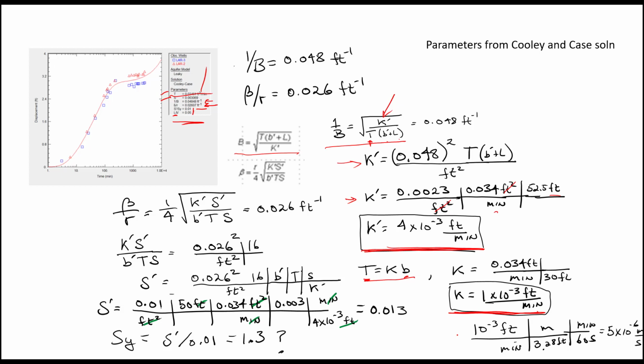And then what I did was just work through here. I use SI units a lot, so I usually think of values in terms of meters per second. So I just went and converted it and got the hydraulic conductivity of the rock is 5 times 10 to the minus 6 meters per second, and that's a fairly reasonable value relative to other analyses that I've done for the fractured rock in the Piedmont. Okay, so that's working with B.